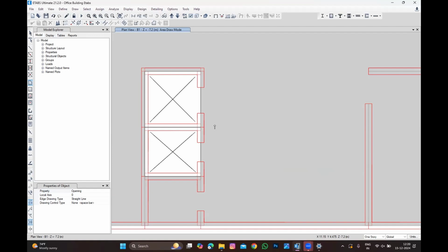Correct. And if you consider the staircase, the base slab one and the opposite one will not be connected to each other. But the base slab rebar pull-out you're taking from the wall. That is for the landing only, connected to the wall. But you will not take it for the base slab from the pull-out bunch.